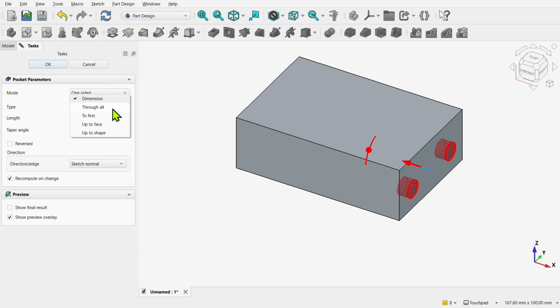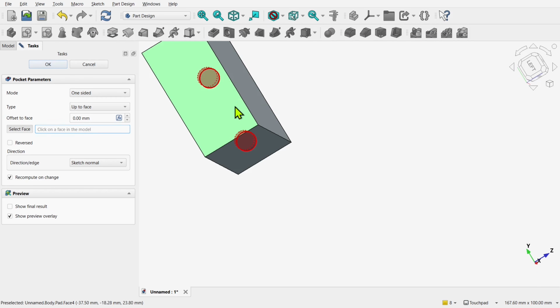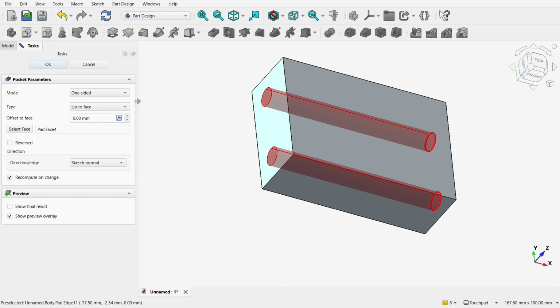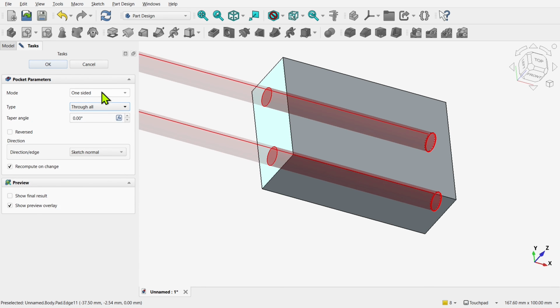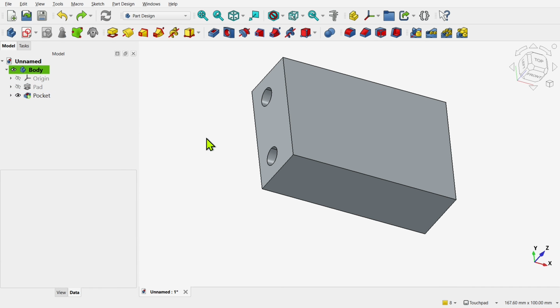We must be mindful of the operations we run as well. Such operations as up to face means that we're referencing the generated geometry. So we have to make sure our operations are compatible. As you can see, it's a longer workflow, but it creates a more stable model.